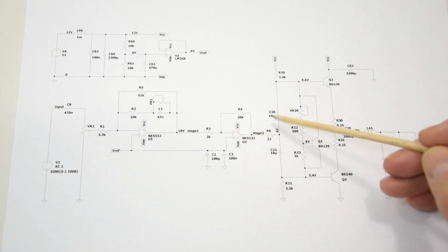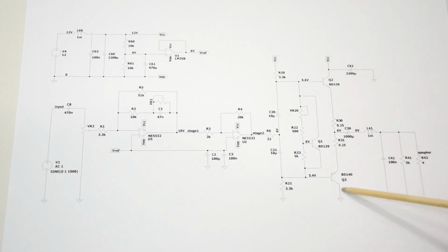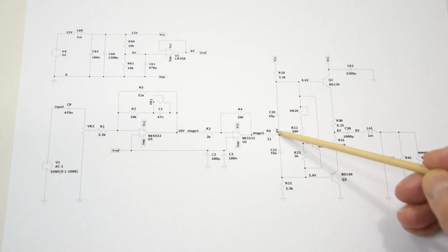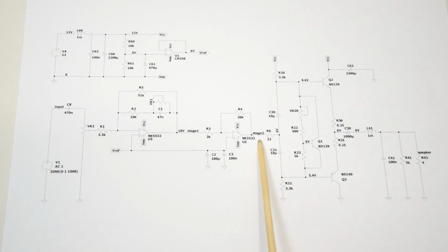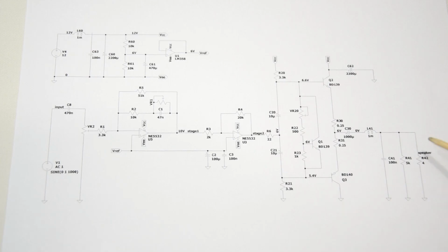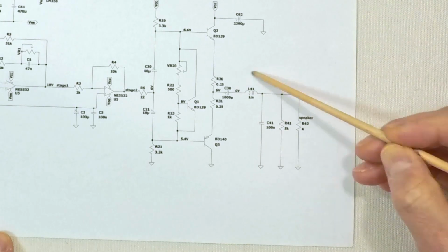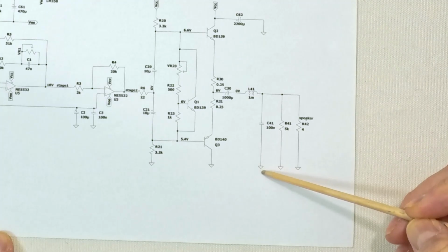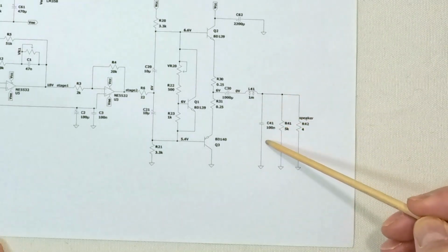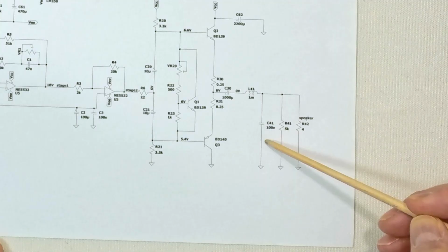If the amplifier is pushed to the max, the output signal can get distorted. It sounds like some kind of oscillation is going on, and by putting in a very low value resistor, the output stage can be decoupled from the op-amp stage and the problem will disappear. So that's an optional one. I've got an optional filter at the output to filter out high frequency noise. It is outside the range of the human ear, but these frequencies sometimes can create artifacts in the audio range. So one could take some measures to reduce that.